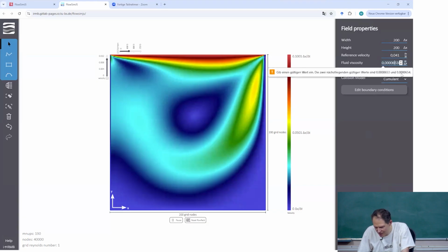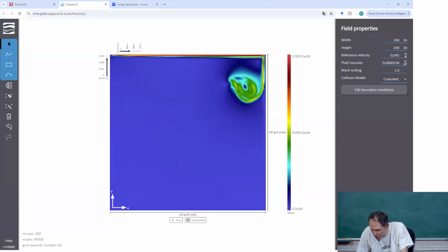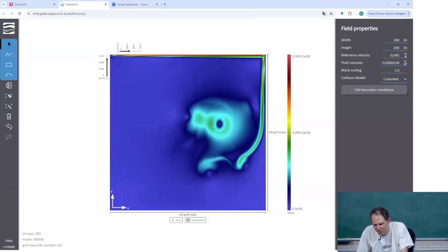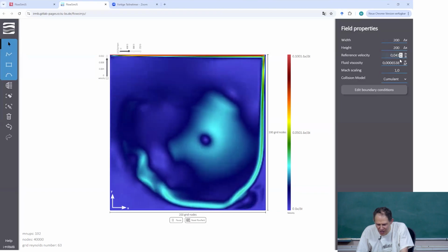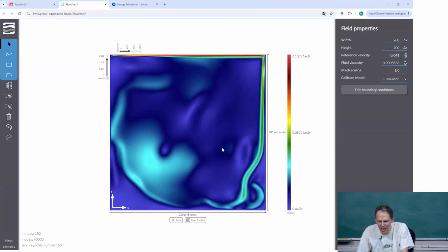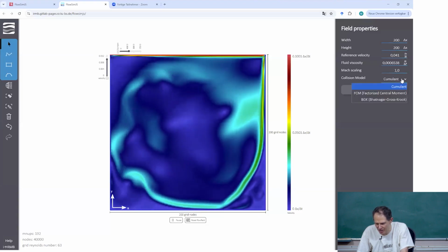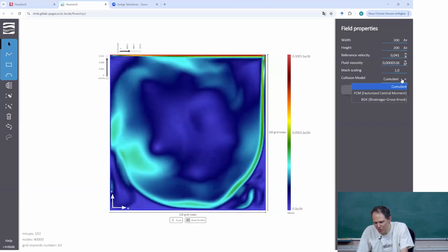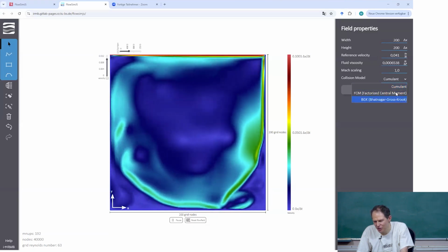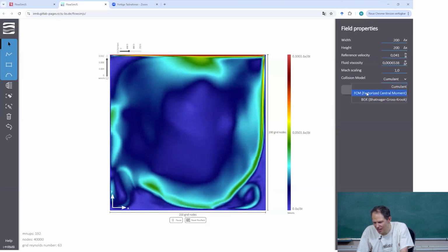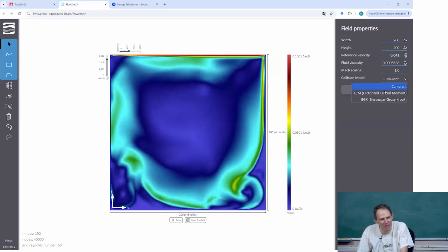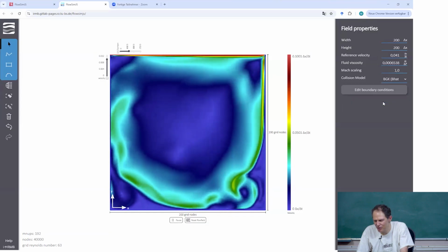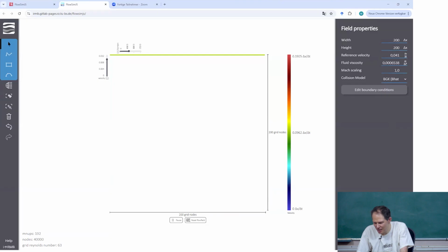Let's make, okay, this was too low, so it does not like to crash, even though it may crash then anyway. Okay, now a lower viscosity means a higher Reynolds number, you see potentially more dynamics. What we are interested in this lecture is different collision operators. Here we have 3 collision operators, where I believe that the FCM, factorized central moments, is potentially not correctly implemented in this. Maybe not a big difference to the cumulants, but we can compare this to Bhatnagar-Gross-Krook.